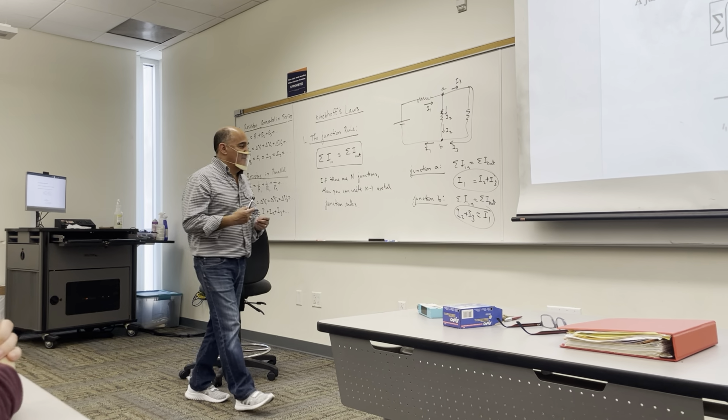This I over here is not me, that I is the current. So that's why I say you. Because you literally take a trip. But I don't want to say I because I don't want I to mean me taking the trip, but also to mean the current. So plus IR if you travel in the opposite direction to the current through the resistor, and if you travel in the same direction as the current through the resistor, then it's minus IR.